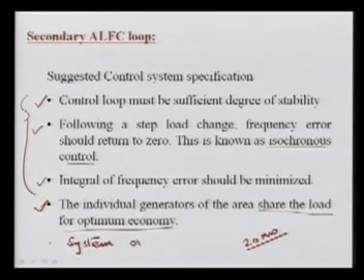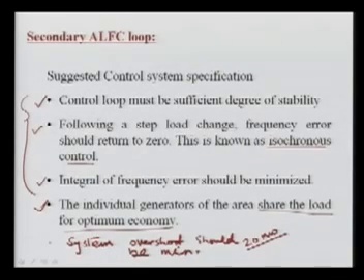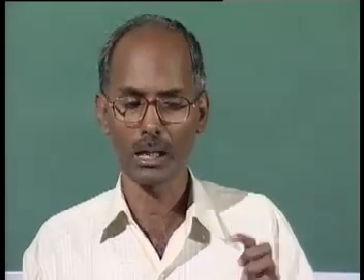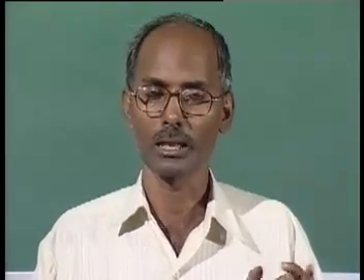The system overshoot should be minimum, because if your overshoot is more, there is a possibility that it may create a lot of problems. We always try to have the minimum overshoot, and also the settling time should be fast enough, and then that is called your control specification.